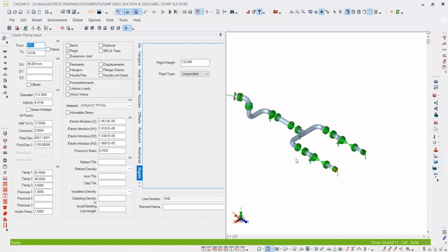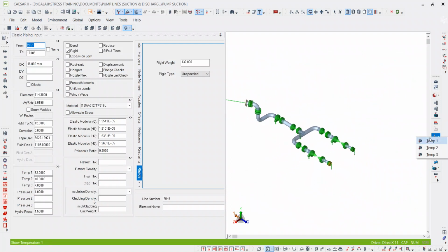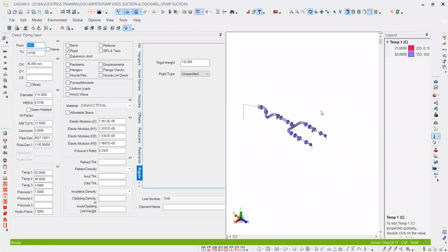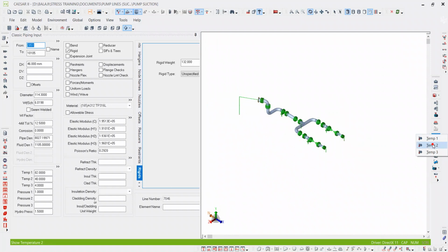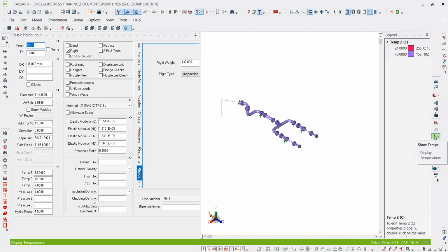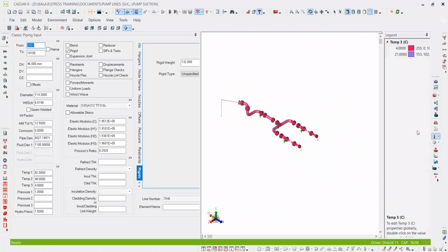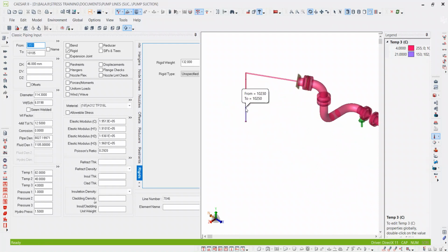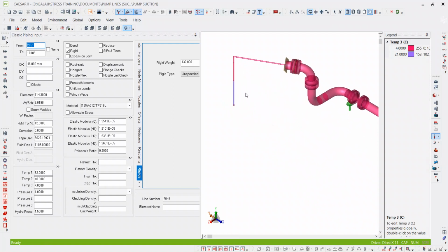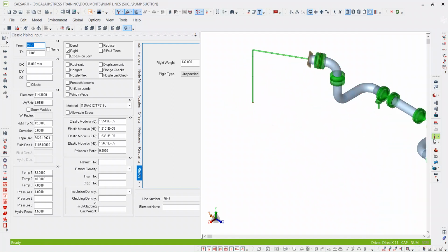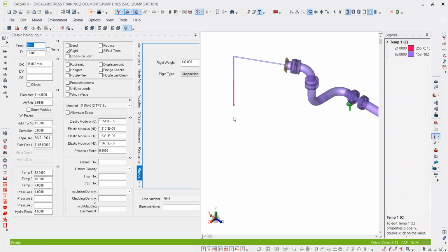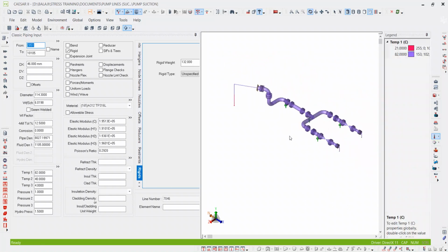So what we will do is the modeling, and we will distribute the temperature accordingly. So far we have given three temperatures: T1 as maximum design temperature, T2 as maximum operating temperature, and T3 as minimum design temperature. In all cases the support saddle, that is the leg of the vertical vessel, is at ambient temperature. We have to use ambient temperature since there is no fluid flow in that particular location. So we have maintained the temperature.